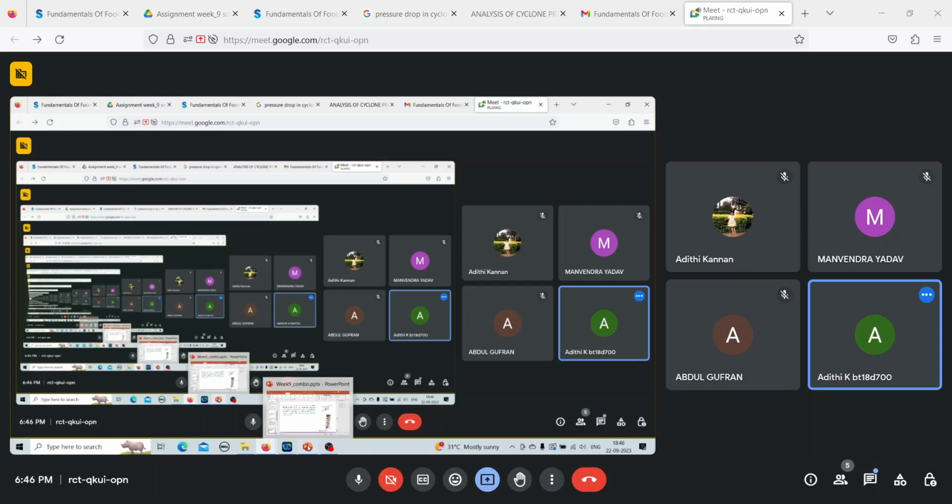So moving on to the last question of the session. A sedimentation tank 1.6 meter wide is fed with a slurry containing starch particles of 30 micrometer diameter and a density of 1220 kg per meter cube. What is the length of the settling tank required to treat 4300 liters of slurry per hour?